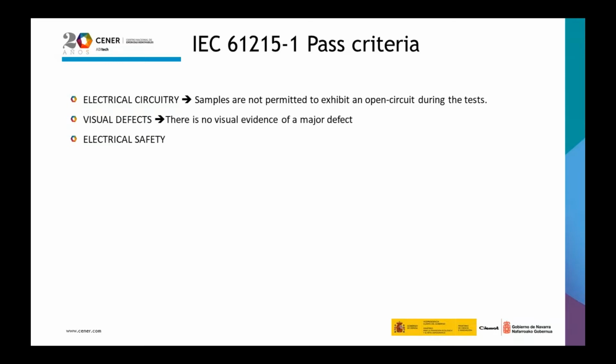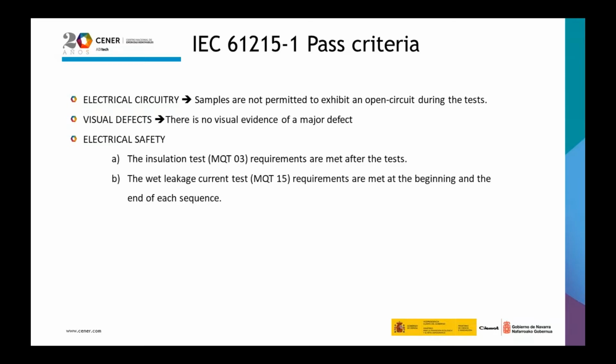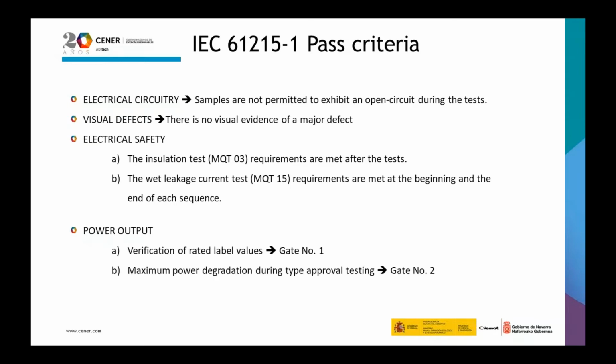And then another pass criterion is electrical safety. We have to check as a final diagnostic that the insulation of the module under dry and wet conditions fulfills the requirements of the standard. And finally, in this standard, as it is a performance standard, we have to check that the output power of the module is the one that the manufacturer declares in the labels.